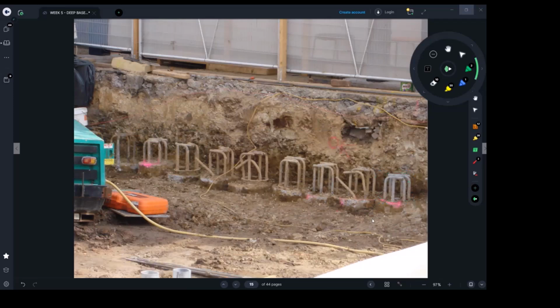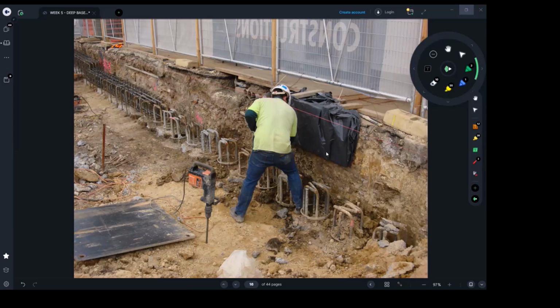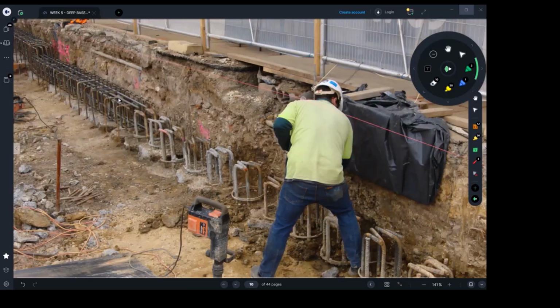Okay, so this is what's happening here, and this is the reinforcement. See, I was telling you the pile cap has to be placed before excavating. So the basement is somewhere here. That's what we're gonna excavate, right? Before you excavate, you have to place the pile cap. The questions that we will ask you are about the steps, the process, what's this, what's that, why we're putting it. So make sure you understand all those details and terminologies, and that's really what we're trying to teach you in this subject.